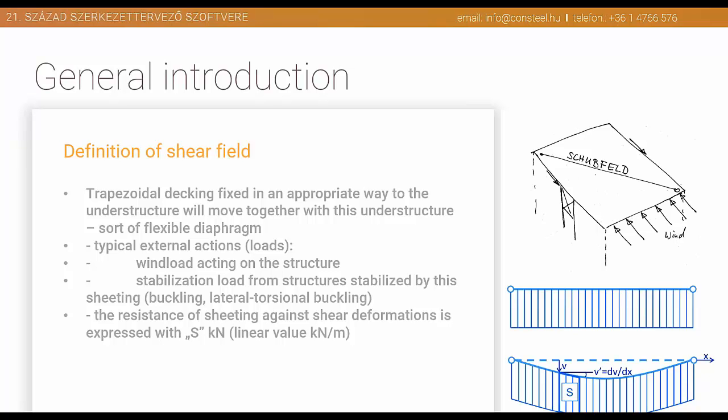It's important to note that such a mathematical model is only applicable for beam elements with 7 degrees of freedom. So it's only ConSteel or some other software which also uses 7 degrees of freedom bar elements. Only such software is able to mathematically consider this effect. Software which uses traditional 6 degrees of freedom is unable to capture this sort of effect provided by the sheeting. So this is something very unique and special to ConSteel and similar software.